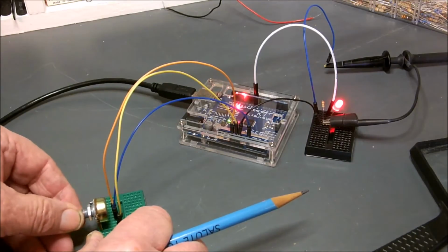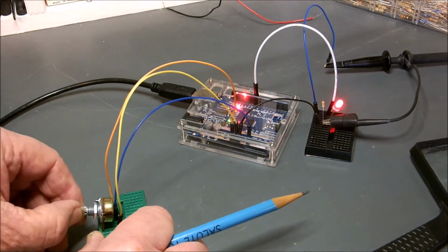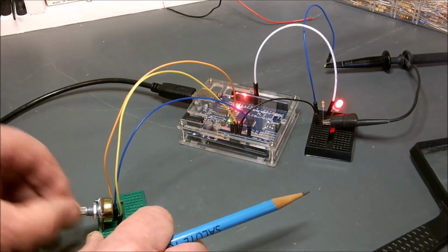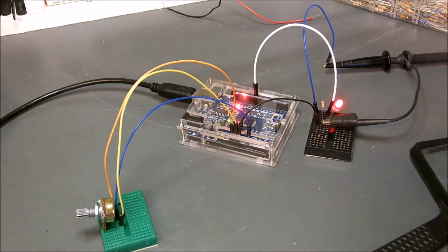And that's being done not by varying the voltage, as one might think we would do, but by varying the time the voltage is on as compared to the time the voltage is off. Switching it on and off very, very rapidly at 500 times per second, which is our frequency, and with different amounts of duty cycle from 0% to 100%. Now we'll stick a motor in line and we'll take a look at that.